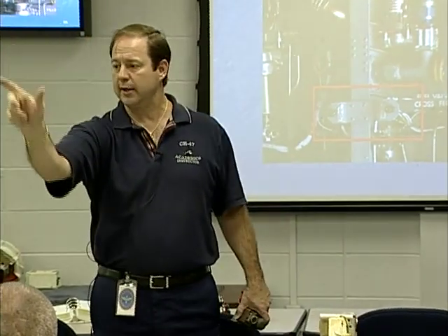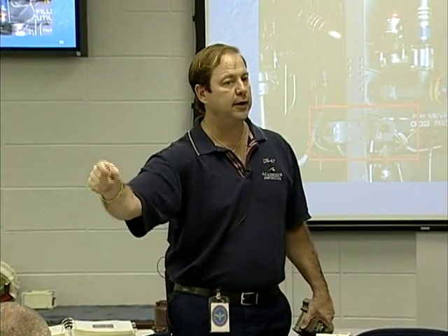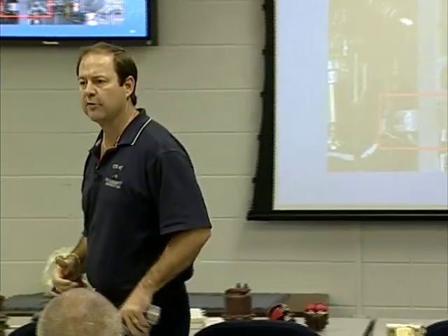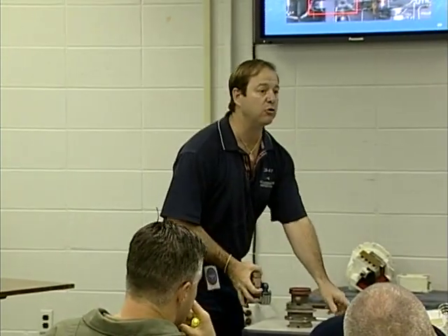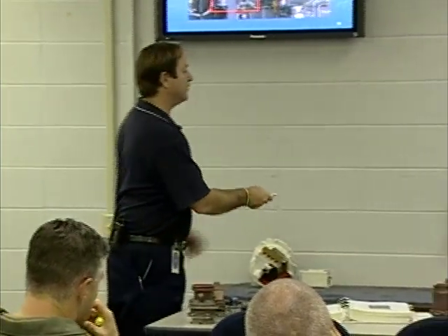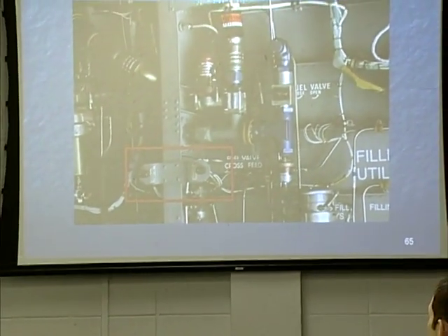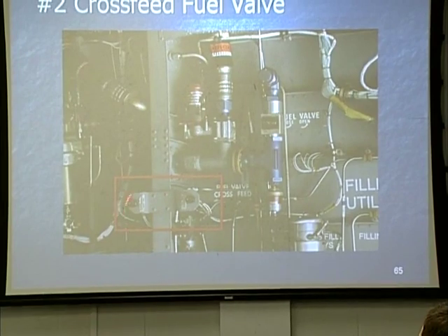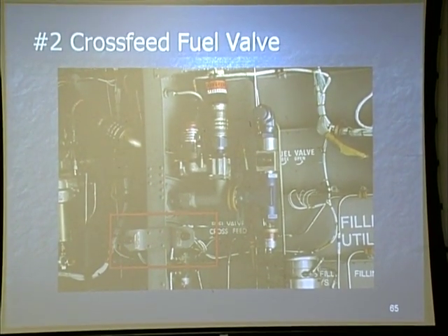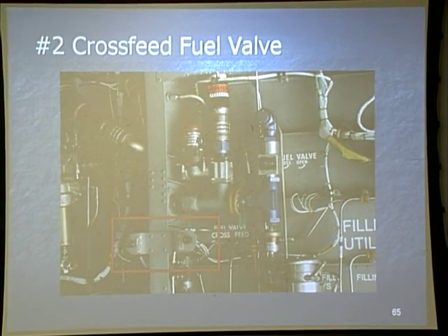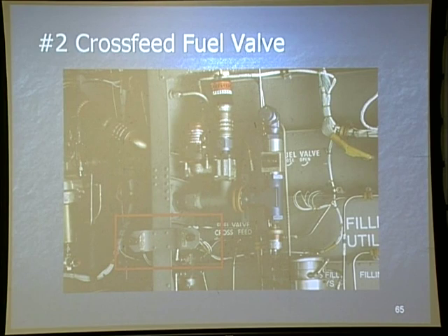And we check them, right? We do our pump check, and then we do our crossfeed closed, and then what are you going to hear from the rear? Crossfeed closed, lights are out. These are the lights they're referring to. But the actual lights they're referring to is the fact that we have one for the right valve on the crossfeed, and we have one for the left valve. Did these lights do anything? No. Why not? I didn't pull the fire pole handle. So when we say lights are out, we're only talking about the lights associated with the crossfeed.